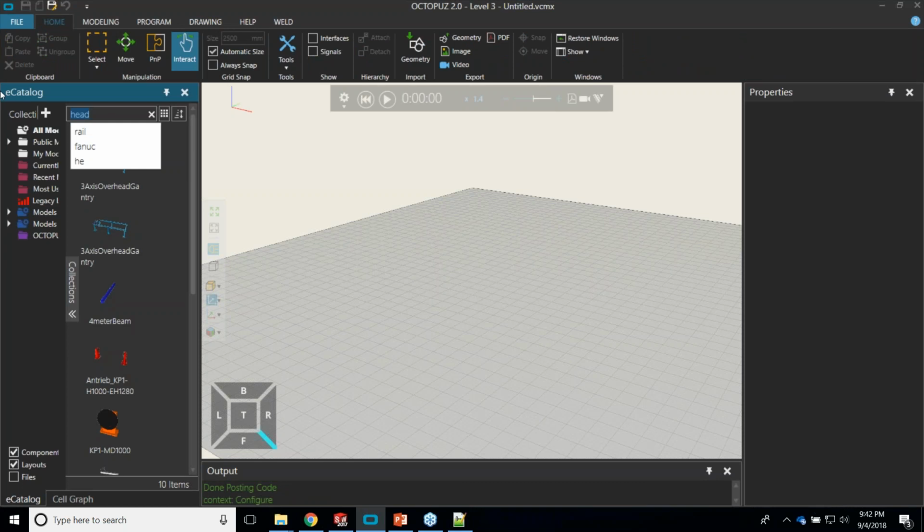Oh, that's even simpler. So 2 robots on the same controller is case by case. 2 different tool center points, or 2 different tools on the same housing on the end of the arm, is pretty straightforward. I don't know all the ins and outs, but that would just be a matter of having two different tool frames set up. Yep. And then you would go inside of your Schema window and choose a different TCP for that tool path.